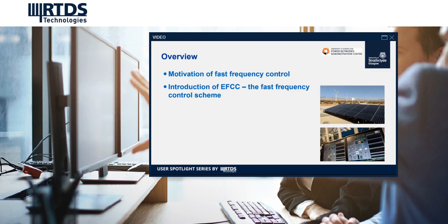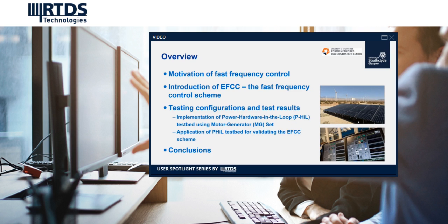I will also discuss how we use a megawatt scale motor generator set to enable a power hardware in the loop test configuration, and how we use such a testbed to validate the performance of the EFCC scheme. In the end, we are also going to share some of the key findings and conclusions from this project.